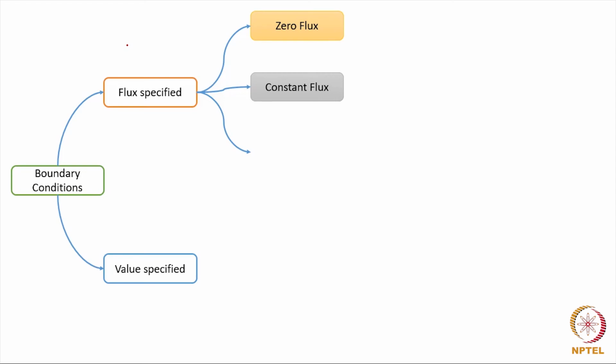So for CVD processes, this assumption would be quite commonly applicable. Often a mass transfer coefficient is also used for the flux. This is analogous to the heat transfer coefficient in Newton's law of cooling. Something very similar can be used for the flux.